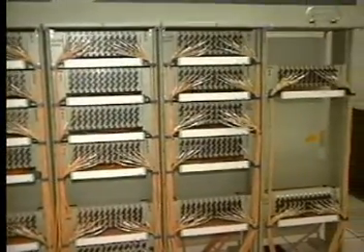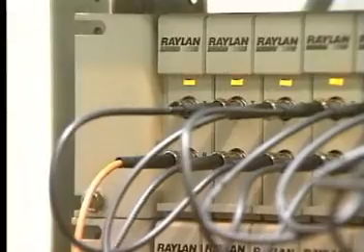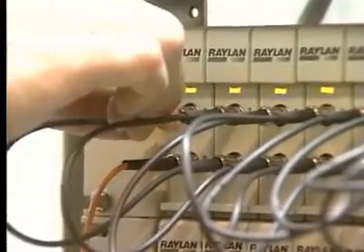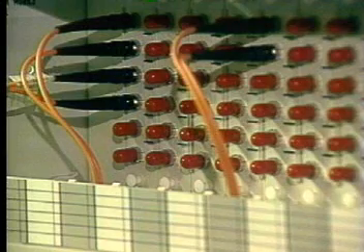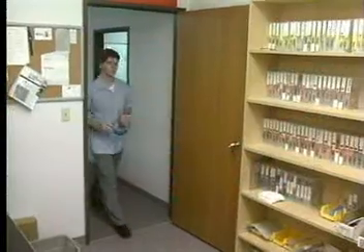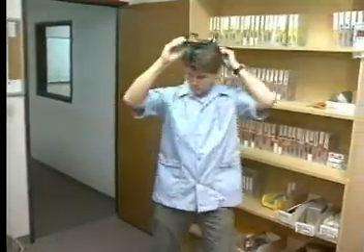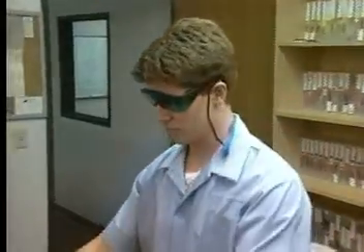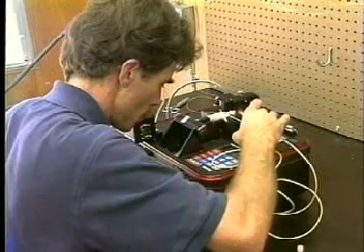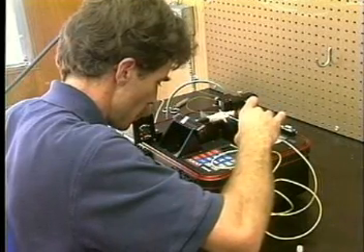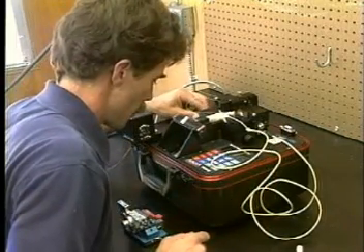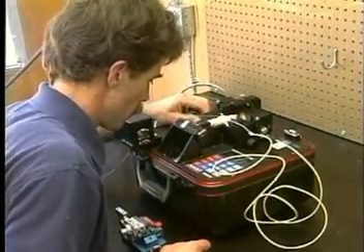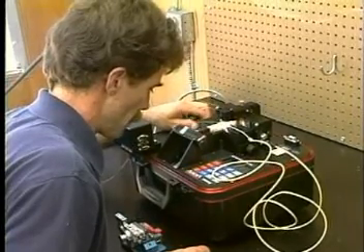Anyone working with fiber systems must follow some simple guidelines to prevent eye injury. Never look directly into any optical port, and unused optical ports should always be capped. When working on systems containing lasers, safety glasses that attenuate the proper laser wavelengths should be worn. Finally, never splice or connectorize a fiber unless the optical source has been switched off. Further information regarding the safe use of lasers is available in the safety videotape of this series.